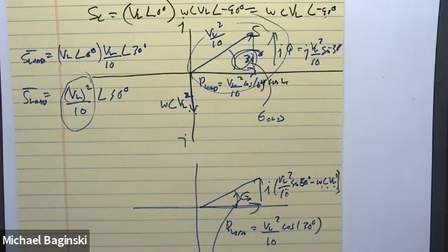Now, the truth is you're going to have variable or adjustable capacitors that will have a variation in values. Usually it's not a knob you turn. It's simply a computer-driven thing where it will automatically find out what the power factor is and then either add capacitance or remove capacitance to get the power factor as close to 1 as possible. You follow me on that, class? That's what really goes on.